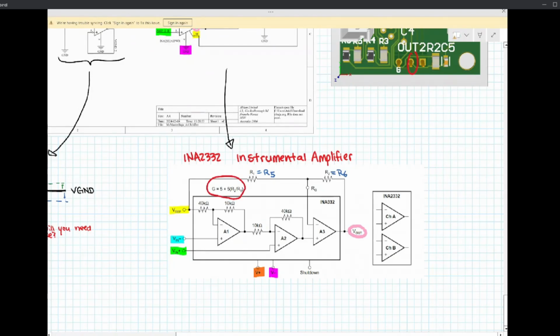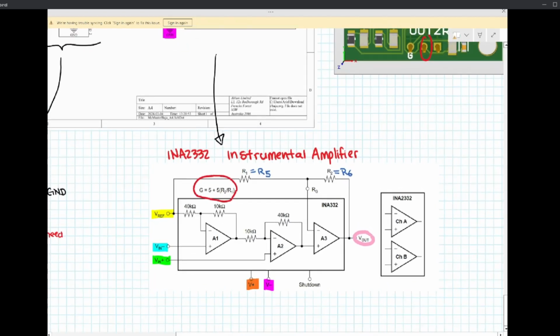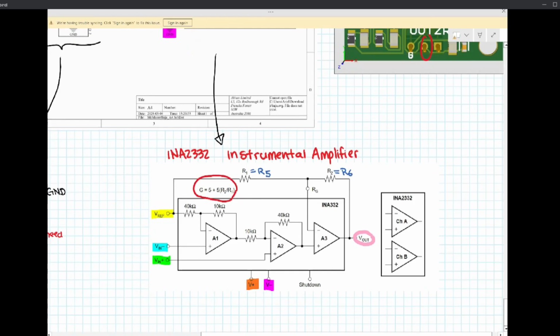The reason why you would want to change that is based on your material. For example, aluminum will tend to deform a lot easier than steel would. And for example, your axles might see a higher strain, like a torsional strain, than your tie rods at any given moment, or maybe even the other way around, depending on the configuration. So you're going to want to amplify the incoming analog values to a different amount to actually make sense of them, and to actually have them be granular enough to be of any use.